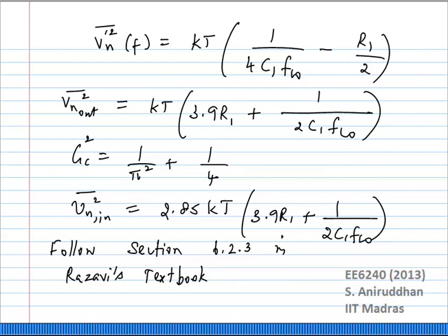Okay, so obviously the passive mixer, as we have seen, can have a large noise figure, but it can also have very good linearity. So the overall dynamic range can be higher than what you would get from an active mixer, especially if you take into account certain things, right? If you're careful with your design, you can definitely do a good job.